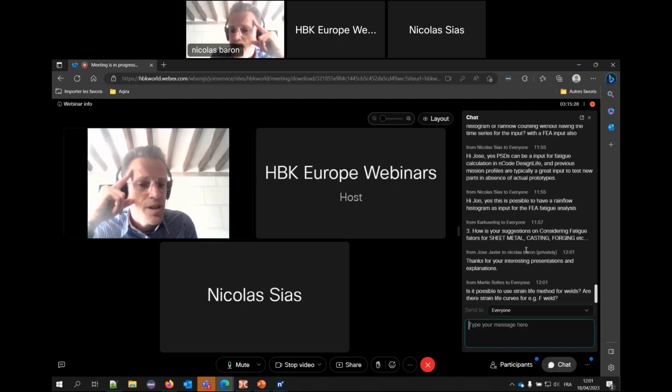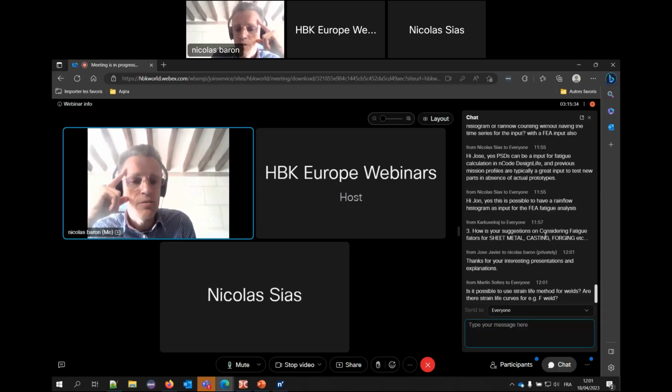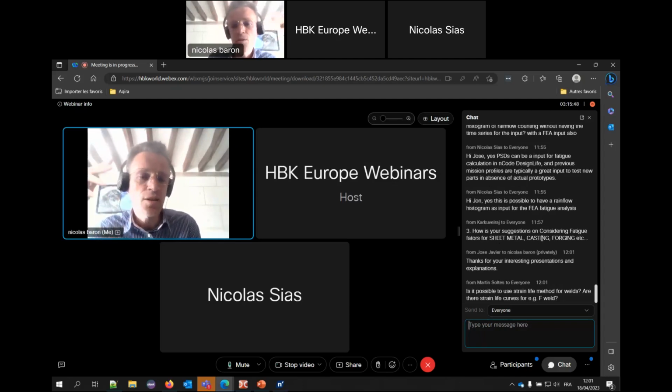How is your suggestion for considering fatigue factors for sheet metal, casting, forging? Well, a very general question here. In the software, we have tools to correct for the process involved in creating the material, whether it is sheet metal, casting, or forging. You can modify the SN curve to take that into account. So in the software, there are ways to account for the different processes used to create your items.